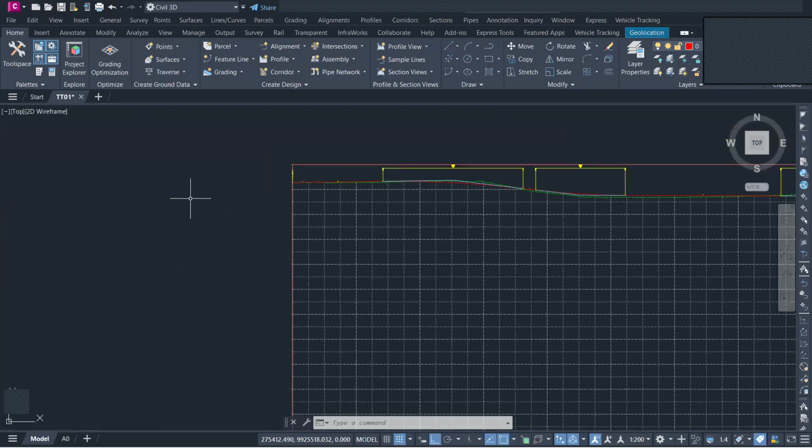You're going to excavate the depth of your subgrade. So what is the recommended depth of your subgrade at that point? So let's say the recommended subgrade at that point is 300 mm. So subgrade 1 is 300 mm.